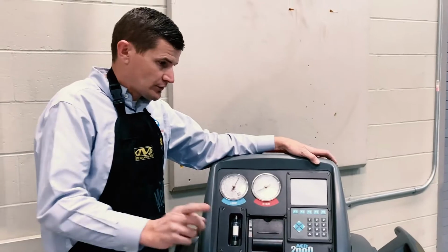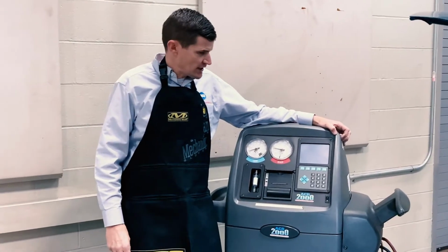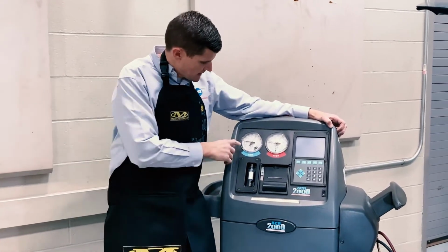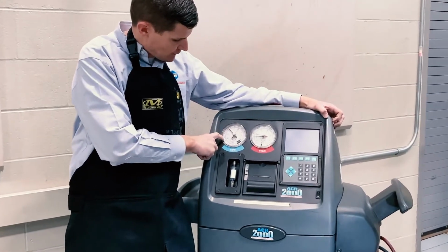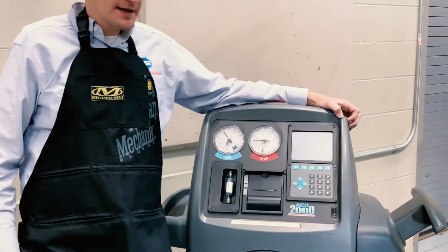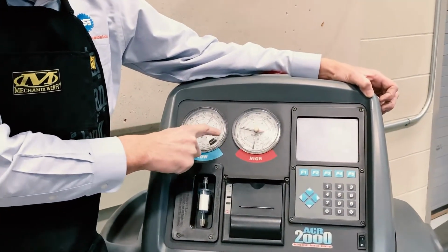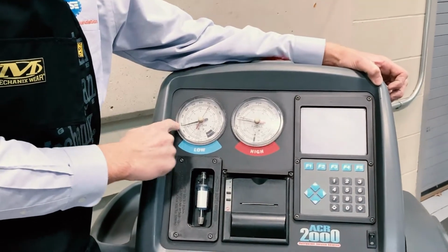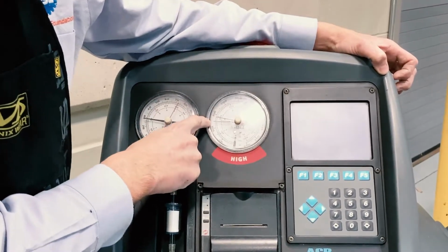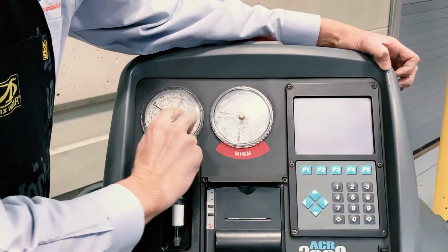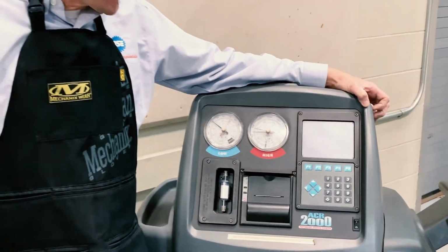So I'm going to start the vehicle, turn the AC button on, and we're going to watch the gauges. All right, so we turned on our machine and our vehicle is running, our AC is running. You can watch that whenever our compressor kicks on, it's going to come down to maybe 20 to 15 psi, somewhere in that range. So you can see that the low side goes down to 20 psi. It's going to cycle off once it hits evaporator freeze up. And you're going to watch our high side gauge start to be about 125 to 140. The system pressures start to equalize here. That's how we cycle the system to prevent evaporator freeze up.